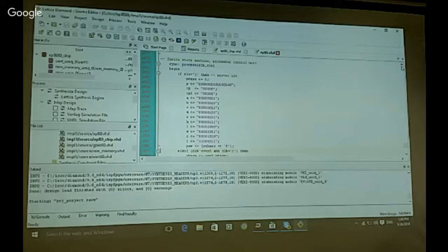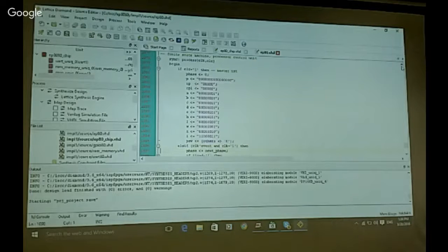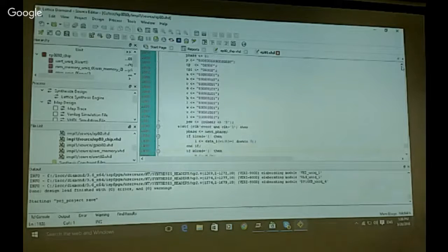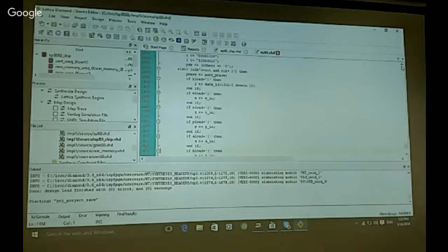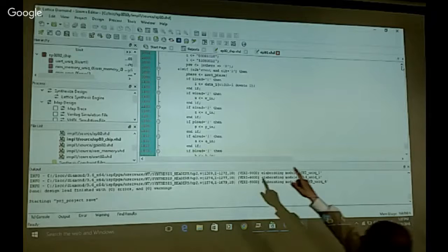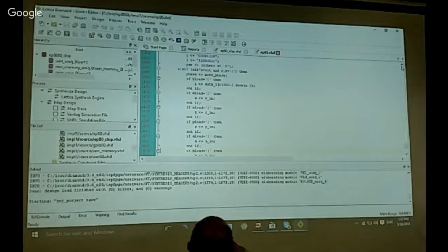And now this is the initialization, and after the clear signal is released, you start to execute instructions. How do you execute the instructions? You control the signal, the clock signal comes in. So clock tick event, and the clock equals single quote 1 single quote. And this specifies the rising edge of the clock. So on the rising edge of the clock, what do we do?